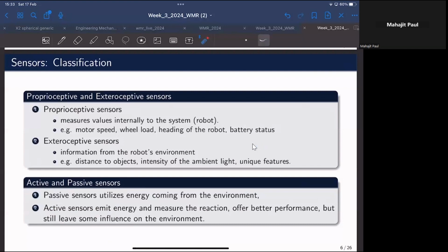You can use the time for the sound wave to come back and be captured by the receiver as a measure of the distance. If you have a transmitter and a receiver here, the time for the wave to go forward, be reflected and come back to the receiver can be used as a measure of the distance for these ultrasonic sensors.